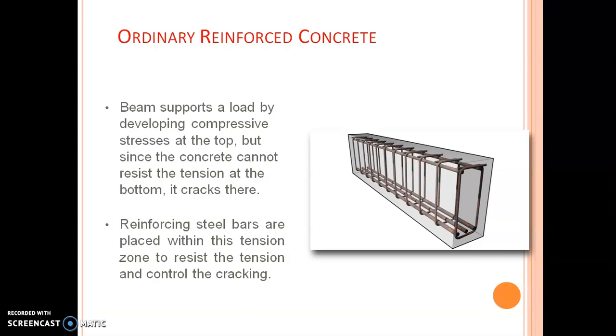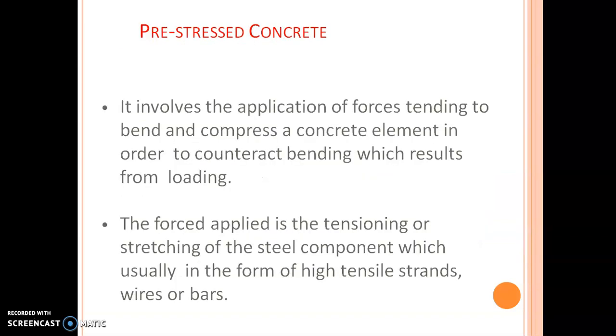Once the reinforced concrete is hardened and the load is applied, the tensile stresses created in the section are taken care of by the reinforcing bars, and the compressive stresses are taken care of by the concrete. But in prestressed concrete structures, as I told earlier, the tendons, the reinforcing element, the strands or tendons, are stressed initially, so that even before you apply load, stresses will be created in the concrete section.